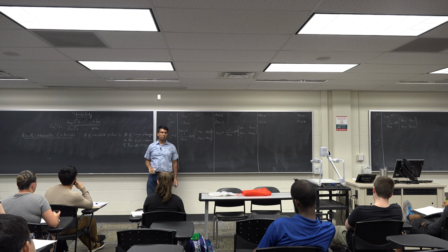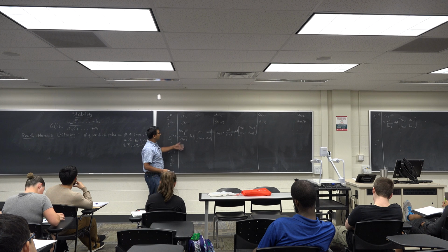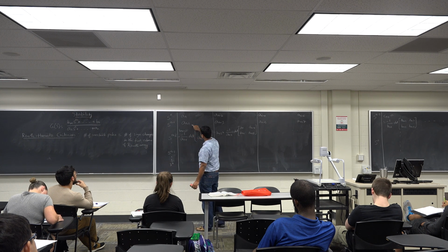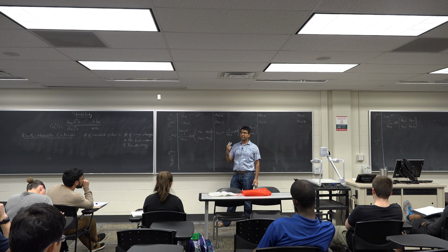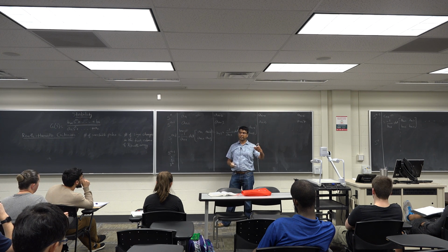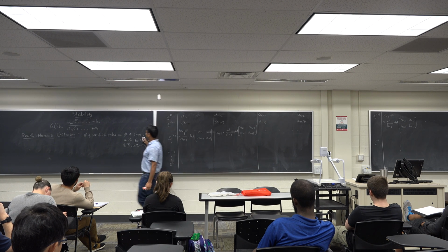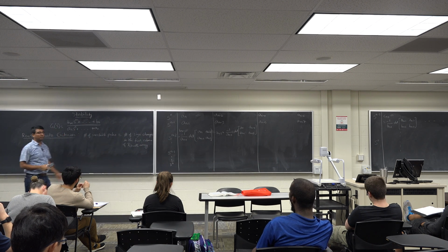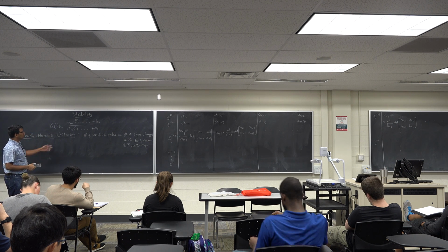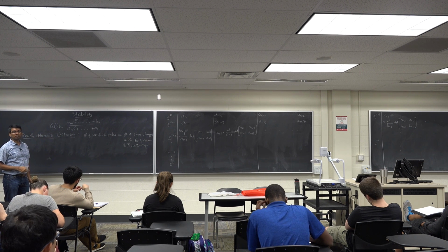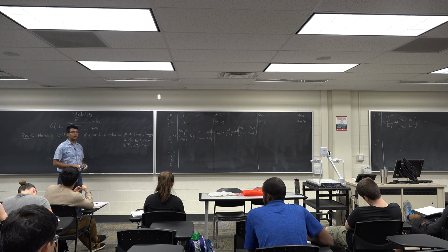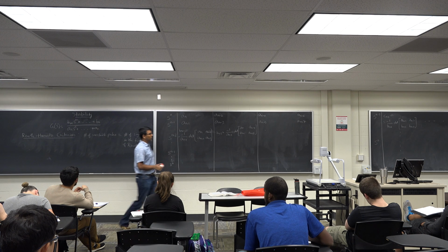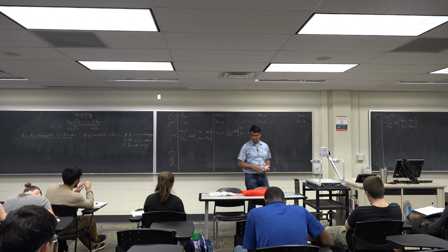If I look at the first column and I see positive, positive, negative, negative, positive, positive, positive all the way to S0, there are two sign changes, one positive to negative, the second negative to positive. So there are two unstable poles in this particular transfer function. There is a long and tedious proof to show this result, which I'll share with you, but I don't expect you to read it.